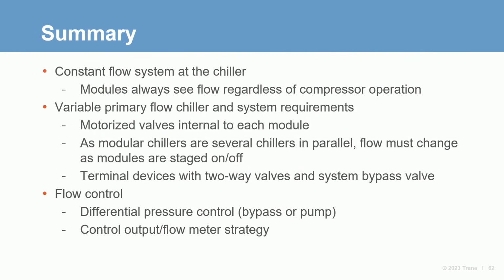Flow control can be achieved in multiple ways. Controlling either the pump or system bypass to differential pressure is a common strategy. Flow could also be addressed with control logic that looks at how many modules are operating and adjusts flow accordingly.